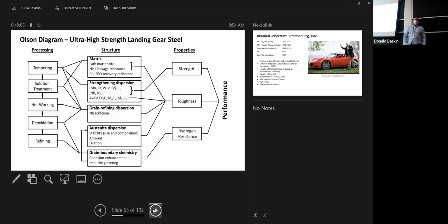The various codes used in the wind turbine industry, like one called Germanischer Lloyd, are kind of a primary specification for lots of things having to do with wind turbines. One of them is steel composition. They specifically spec steels for applications like offshore wind turbines that have niobium content in them. Niobium is able to strengthen steel not only by keeping the grain small, but also by forming very fine precipitates.